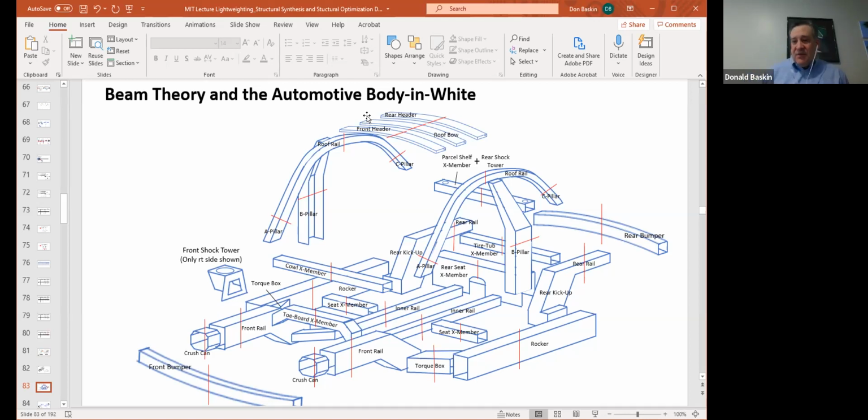I don't know if you've seen that. I think it was in the late 2000s, the 5 Series was one of the first cars to use a cast aluminum shock tower. So this part right here got cast out of aluminum. That's also to reduce the weight of the front of the vehicle and shift the weight distribution rearwards. As you get to these bigger and bigger engines, right? You put a V12 in there, it gets pretty hard to get 50-50 weight distribution, because the engine weighs so much.